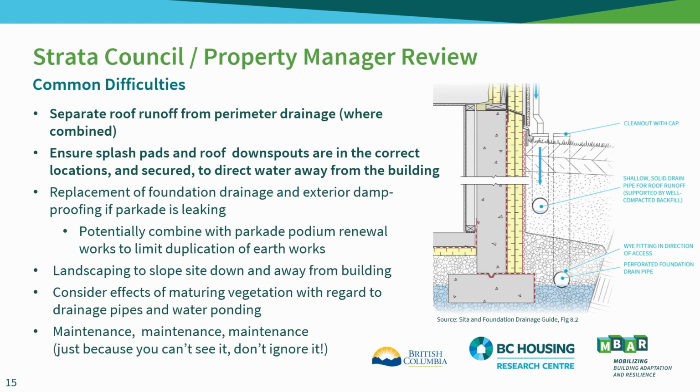If the parkade has active signs of moisture ingress, consider engaging a professional to look into risk assessment and renewal options. If the podium membrane is scheduled for replacement, it would be prudent to assess the function of the perimeter drainage so that targeted maintenance and repairs can be carried out when perimeter excavation is already partially advanced.